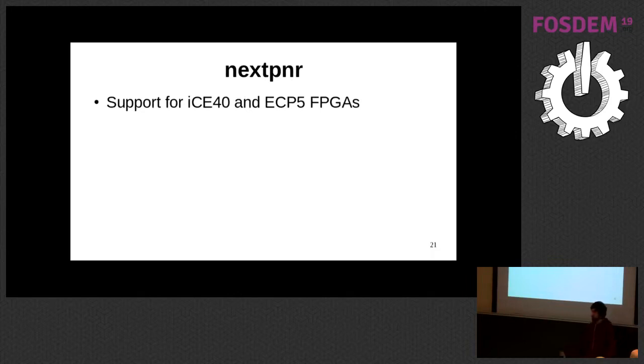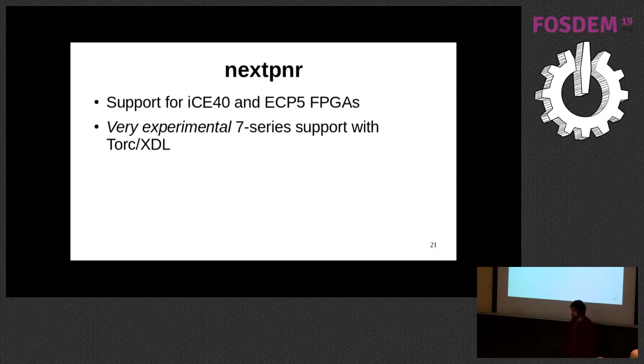So nextpnr has good support for ICE40 and ECP5 FPGAs. There's some more experimental work going on with other FPGAs. There's very experimental support for Xilinx 7 series, using not a full open source flow, but using Torc, which is an academic project, to get the device database, and XDL going through ISE to do the bitstream generation. But this is very experimental. It's mostly for doing research on very big FPGAs. It literally just supports LUTs and flip-flops, no RAM, nothing fancy.